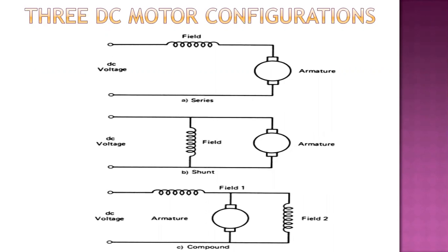So this motor has a smaller starting torque but good speed control characteristics produced by varying armature excitation current. If you find out the applications where it is used, that is, where speed is to be controlled, such as a conveyor system, in that case the shunt type motors can be used.